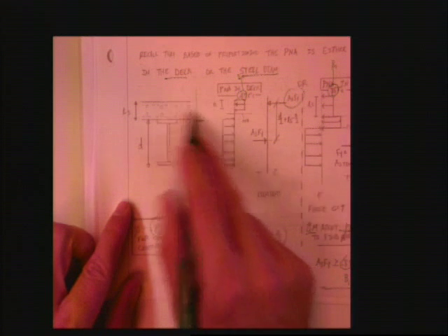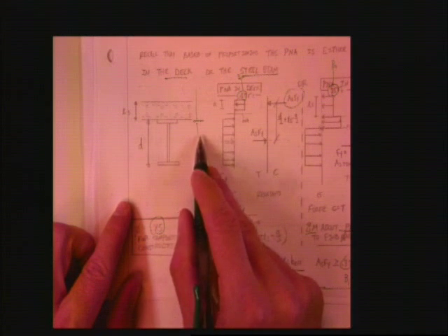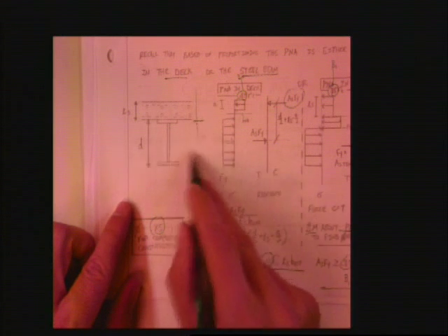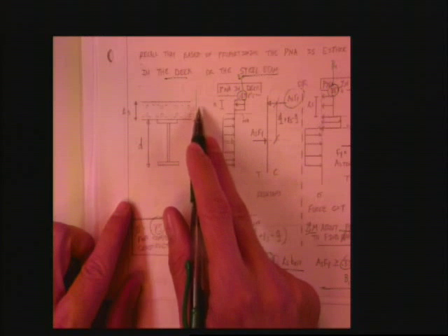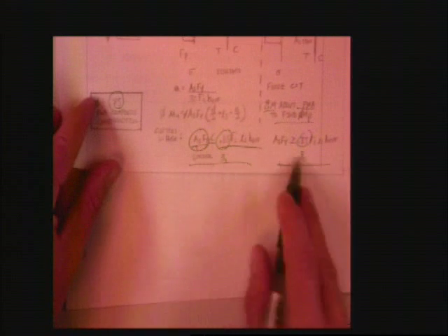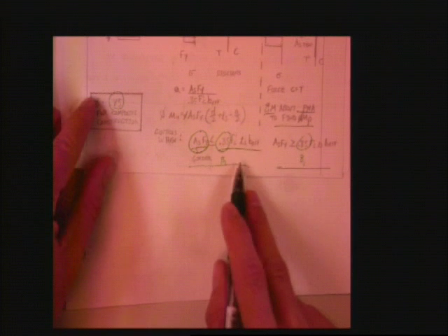If the resultant forces are higher above this point, that means we have to move the neutral axis down. If the sum of the forces are larger below this point, that means we have to move the neutral axis up. All right? And this math does it for you right here. It's doing the same thing. Okay? Of course, be careful.